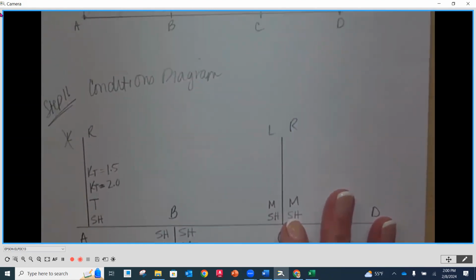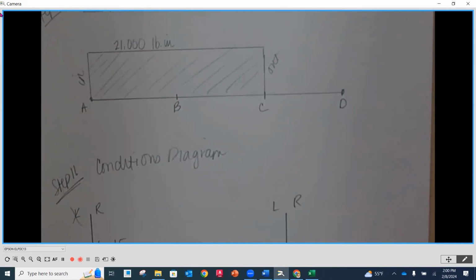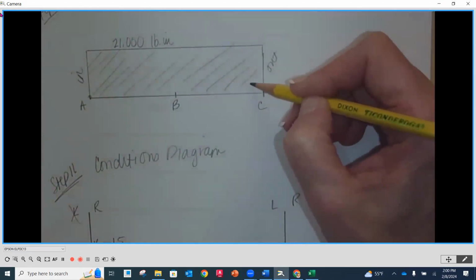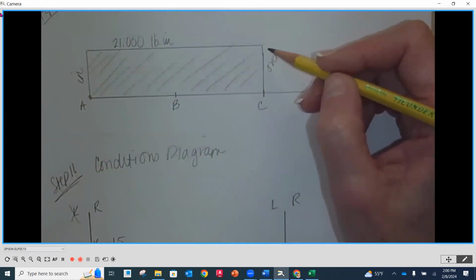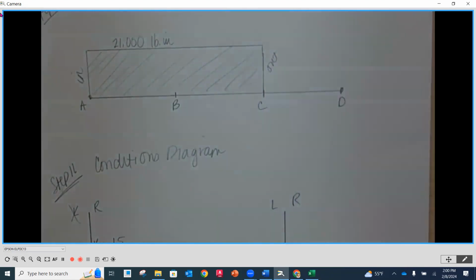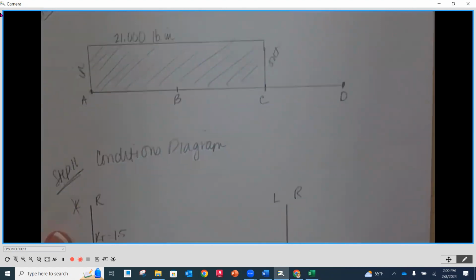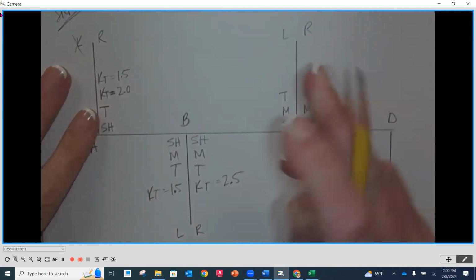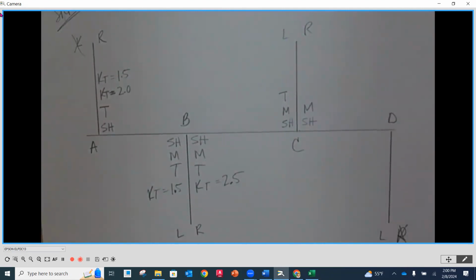Now we're going to go up to our torque diagram. Here's our center line of C. Left-hand side, torque. It goes out on center, no torque on the right-hand side. You guys see that? Okay. So we're going to go down here. Torque on the left-hand side. I'm going to leave torque off. I'm not even going to put a T there at all. Nothing for torque on the right-hand side.